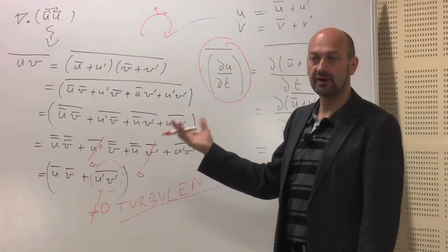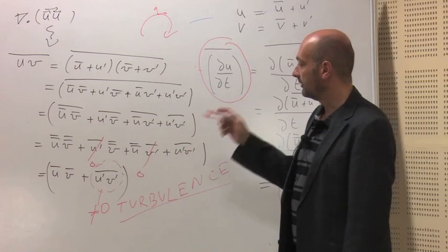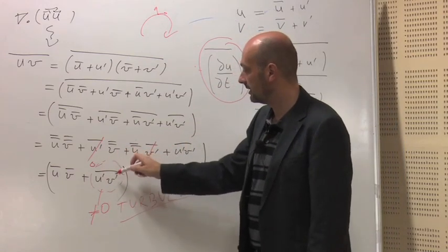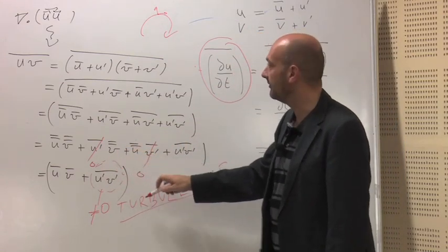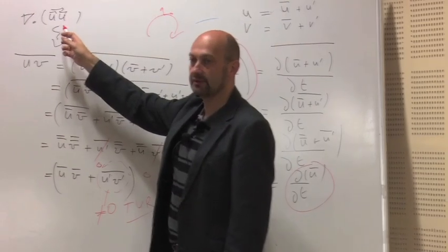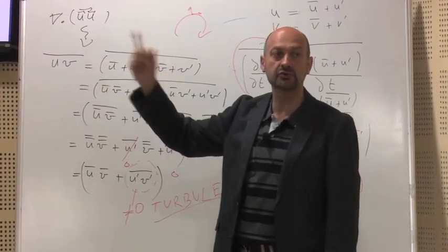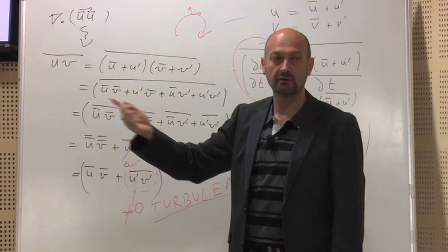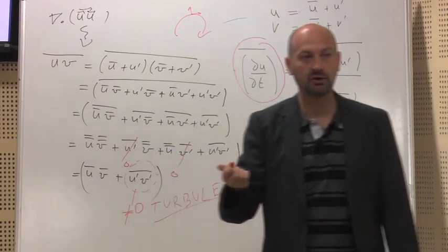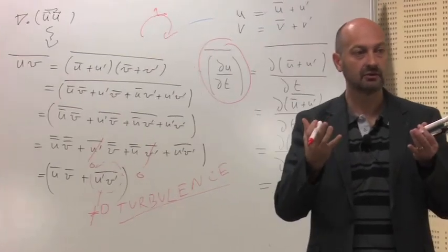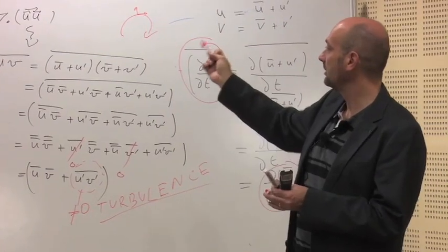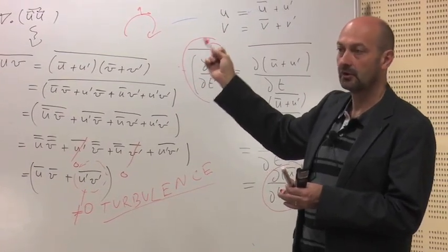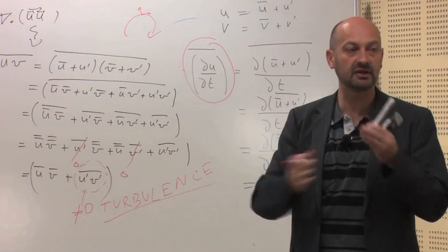And the beauty of the Navier-Stokes equations is you see that these terms are related to turbulence, and they are coming from the nonlinear terms, which is the source of the turbulence. Because when you increase the Reynolds number, you increase inertia. When you increase inertia, you increase the weight of that term. So you see that everything is connected.